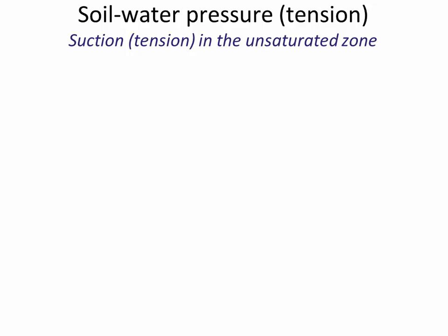That's oversimplifying the situation. Because even above the water table, there's still moisture in the soil. It's just that below this level, all of the voids are completely full. Above this level, some of the voids have water in them. Those small little voids have water above the water table because of the capillary effect. And there's probably moisture close to the surface because, remember, during infiltration the water is moving through.